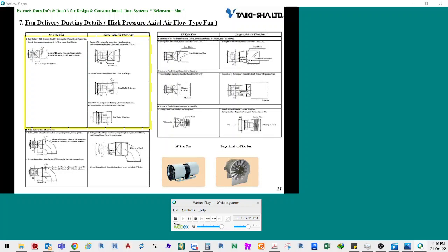If a large-size axial flow fan is used, a rectangle to round duct, whose dimensions are the same as the fan, is installed at a length of approximately 0.7 d, and an extended duct is installed. A standard extension cone can be installed. Among large-size fans, the compact-type fan has an outlet opening 2 sizes larger than the base of the outlet, so a standard extension cone can be connected to it.